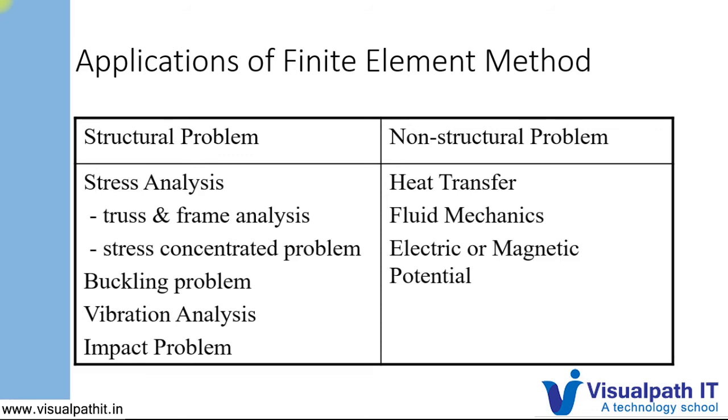So we need to know what the natural frequencies of that system are, and whether my load is going to excite that system, and even if the load is going to excite the system, whether the system can withstand those loads. Those things are involved in the vibration analysis. We usually call them dynamic analysis also, but there are many more vast areas that are included in dynamic analysis. Those also can be done using finite element analysis in structural problems.